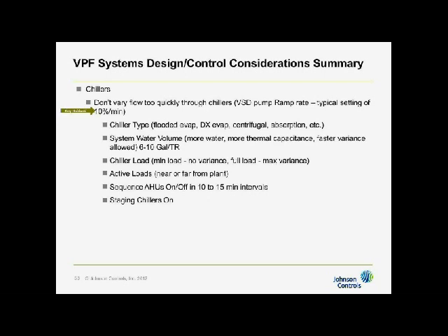That doesn't mean they can't go faster. You can set these maybe up to 30. Some systems are 5, some are 10, all the way up to 30. It's not the chiller determining exactly how fast you can go. It's the system determining it for the chiller, okay? The way you set this is typically in the variable speed pump drive controller.